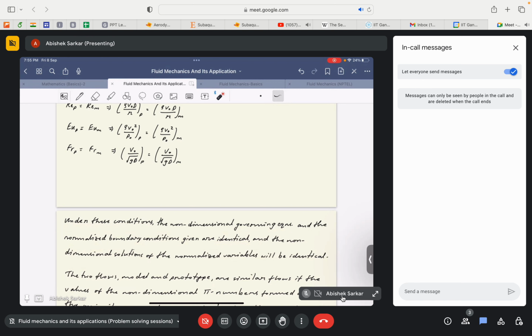So basically it's actually vice versa. You will see that the first approach tells us that from the governing equation itself we get an idea of what are the non-dimensional numbers that will come into the picture. So we equate those non-dimensional numbers and compare them by knowing which among these will actually govern the flow, and once we know that, the other forces or factors can be neglected, and then we compare these two driving factors that drive the flow, and then finally get a conclusion, and then compare these two non-dimensional numbers.